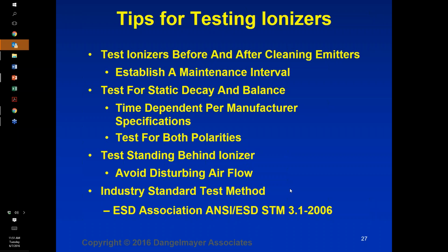At some point you'll find that the ionizer no longer meets your performance requirements. It's drifted beyond them because it hasn't been cleaned, and now you know that you need a shorter maintenance interval than the time you've waited at this point. So when you first start using the ionizers, we certainly recommend checking them monthly, but if your ionizer is still within your performance requirements, there's really nothing that you need to do at that point.